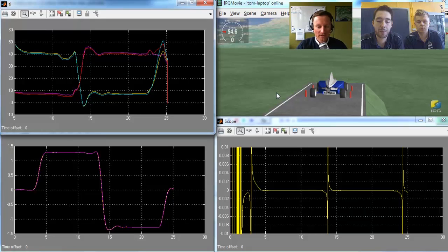And if we have a look at the steady state cornering, the understeer coefficient is 0, so we can assume that almost no understeer is happening, right? Yes, exactly. Okay, perfect. This is a pretty impressive demonstration of how a yaw rate controller can help your car behave optimally. Can you give an estimate on the time you actually saved by applying that controller? If we enable the yaw rate controller during a skid pad, it will save a few tenths of a second. And actually a fraction of a second can make a big impact. Right.